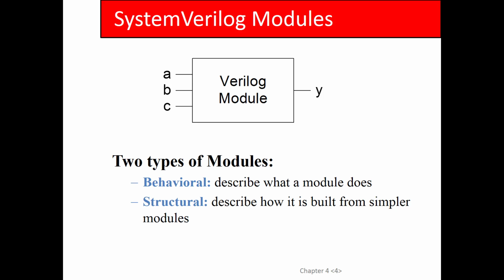Okay, so how do you write Verilog? Well, the first thing you have to understand is there's two types of coding styles in Verilog and VHDL. There's behavioral and structural. Behavioral is when you're writing code that implements a truth table or a state machine. You guys with me? Because ultimately, that's the only thing hardware can do, is a truth table or a state machine. Those are the only two functions that digital logic can perform.